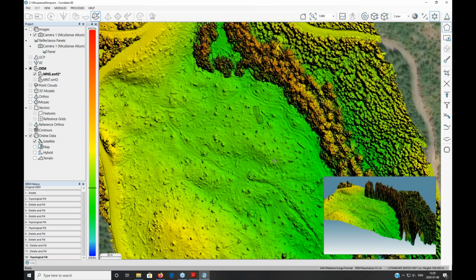We also have other tools to edit the overall DEM for the best output possible. We have tools to remove elements respecting the topology. You can crop certain areas, you can flatten out certain areas. If you have maybe a water surface, you can flatten out those areas. You can filter out some areas based on a mean or median filter. And once everything is done, it can be exported as a GeoTIFF file. So the surface model and terrain model will be exported as a GeoTIFF file.